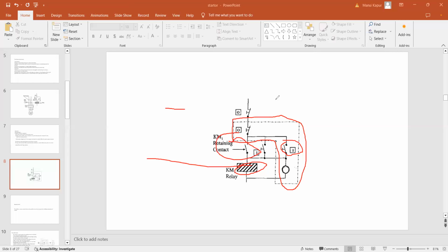You must have seen there are some motors in the engine room which we can start from multiple locations, right? Like our supply pump and circulating pump, we can start from ECR and we can also start from local. Understood? But if you stop and lock from any position, then you cannot start.